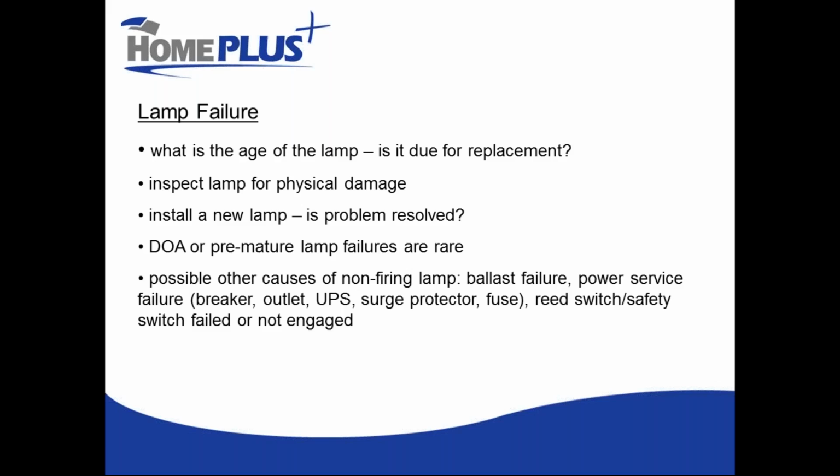We would have pre-submitted a proposal for how the chlorine contact was to be run at the end of the contact time, or the end of the contact vessels. And I will guarantee it was not designed to be up that high. The maximum we ever designed to is 1 milligram per liter. That's good information. So you should be able to reduce that a lot.